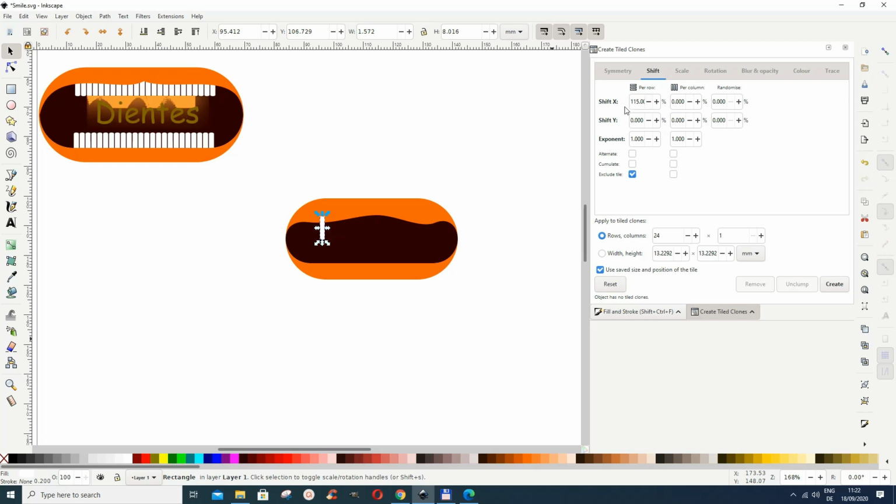And then what I want you to do is go to shift, and when you go to shift here, put 115, so that we move this about 15% next to this, the gaps in the teeth. You can also make it 120. I tried 150. The one photo there was done with 115. Let's try with 120 to see the holes that might come out of it.